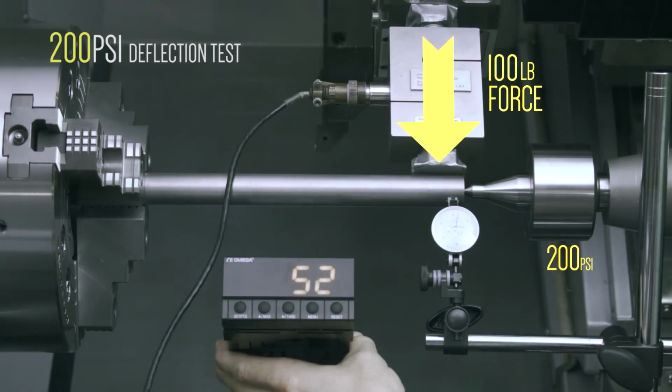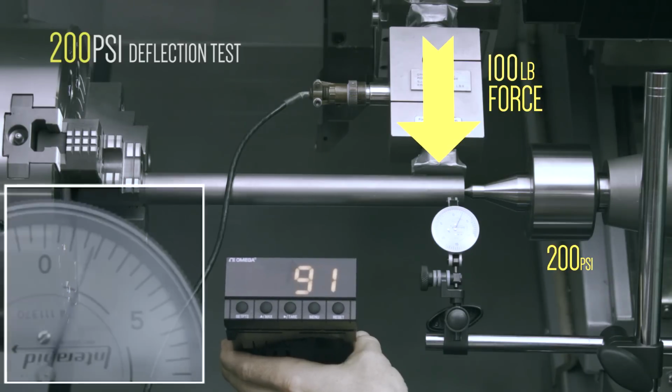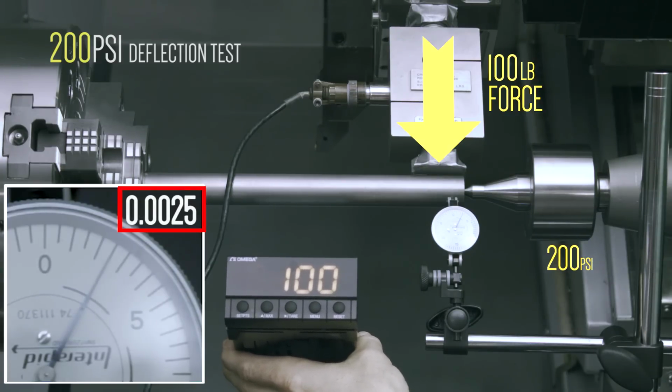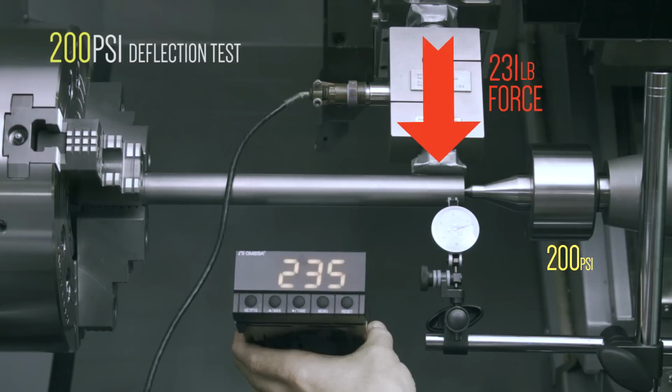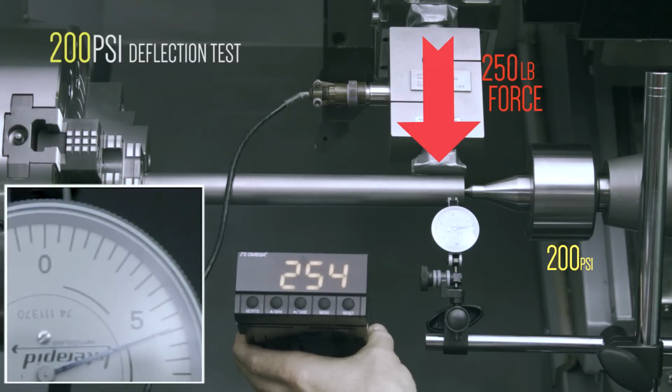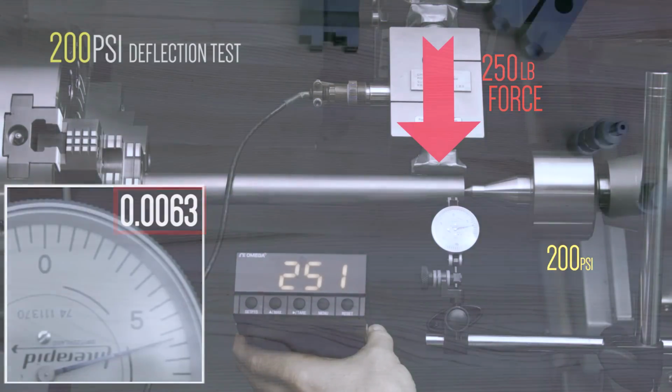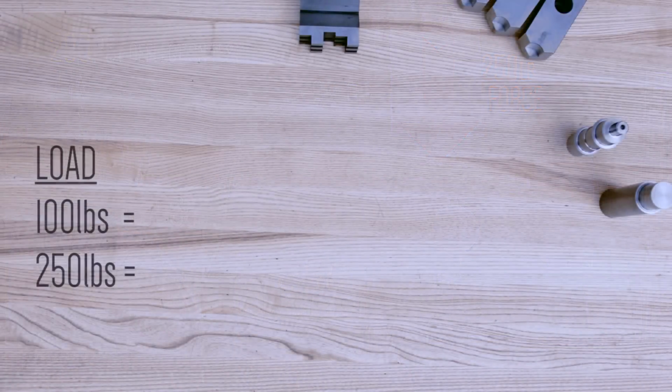Okay, so we're jogging X-axis in tenths mode to apply a radial load of 100 pounds at the end of the workpiece. The end of the shaft deflects 2 thou 5/10. Increasing the load to 250 pounds of force, we get a reading of 6 thou 3/10. Here is a summary of these results.